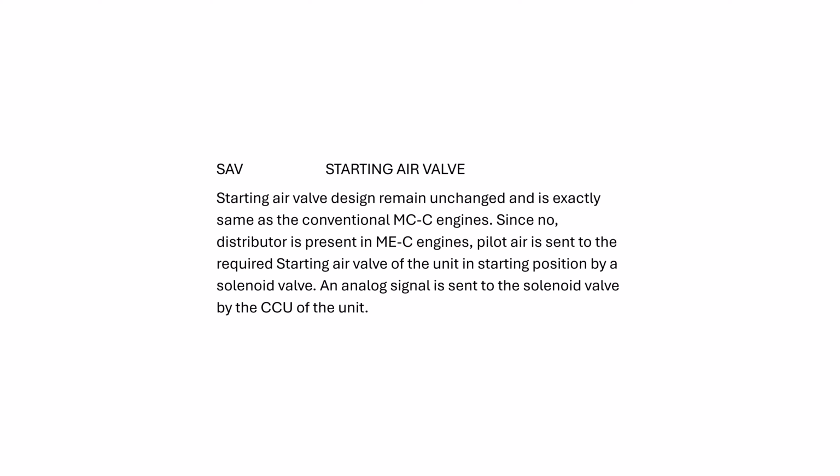Starting air valve design remains of course unchanged. The starting air valve is exactly the same as the conventional MCC engine. See, no distributor present. The pilot air is sent through the solenoid valve. A solenoid valve is controlled by the CCU. That is the only difference.